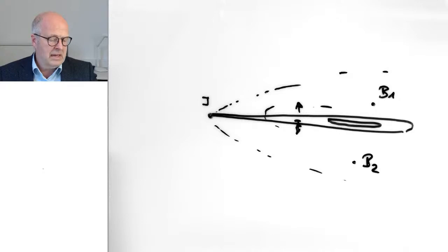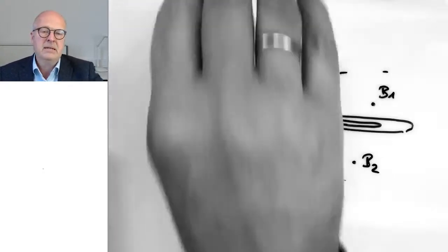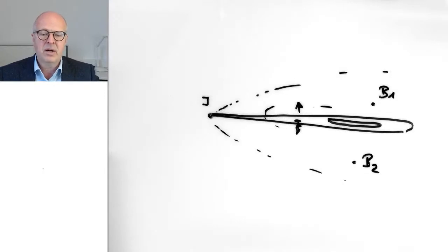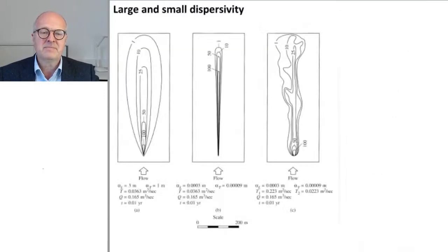If you understand the dispersion of tracers, you can at least develop an idea of why a tracer experiment fails, or you can calculate the width of the tracer cloud at a certain distance. Now the right hand example is also interesting. Here we have heterogeneous material, which is normal in fact, so the tracer dispersion is not as regular, and the amount of dispersion changes all the time.